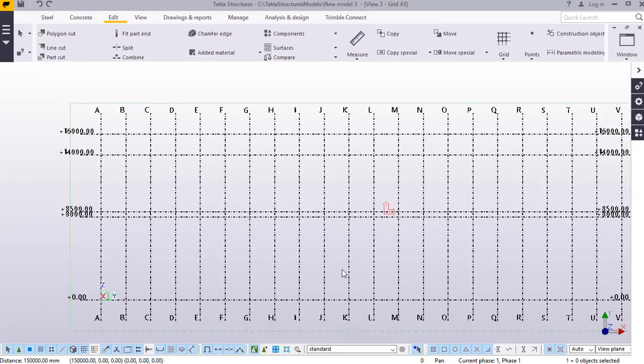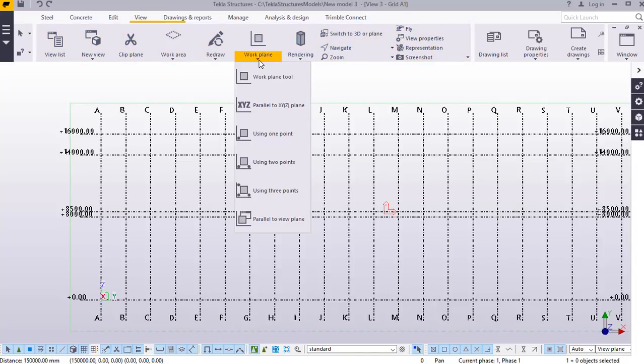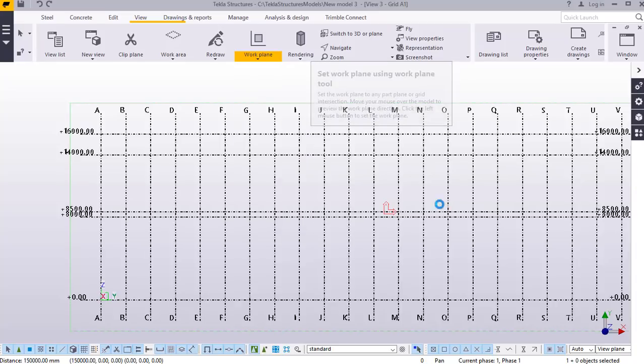And prior to moving ahead, you must reorient your x-axis to take the position of y-axis. I mean, you have to create your curved truss on the x-y axis. And to change your axis, you just come to view. Under view, you come to work plane tool. You click that drop down arrow under work plane tool and pick work plane tool command right there.